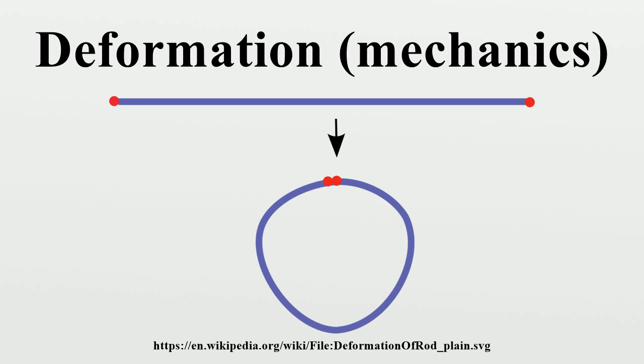Deformation implies the change in shape and/or size of the body from an initial or undeformed configuration to a current or deformed configuration. If after a displacement of the continuum there is a relative displacement between particles, a deformation has occurred. On the other hand, if after displacement of the continuum the relative displacement between particles in the current configuration is zero, then there is no deformation and a rigid body displacement is said to have occurred.